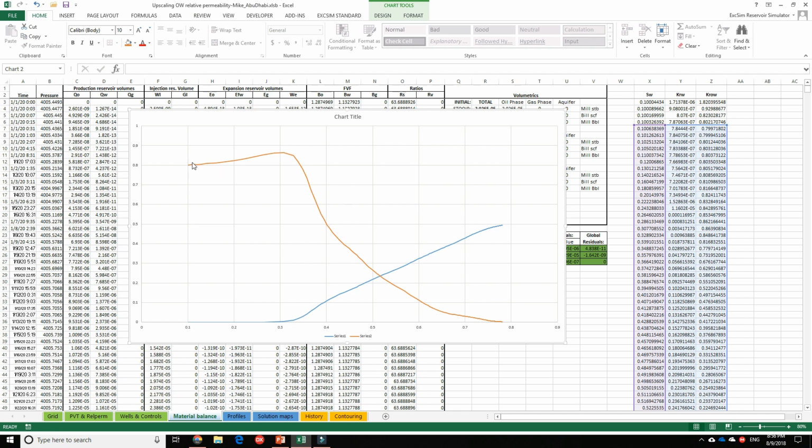But then as the model gets filled with more and more water, and water is less viscous than oil, the mobility of the system increases. So the water rate will actually increase until it breaks through in the first high permeability layer, and then that high permeability layer will produce only water, so the oil rate drops, and so on.